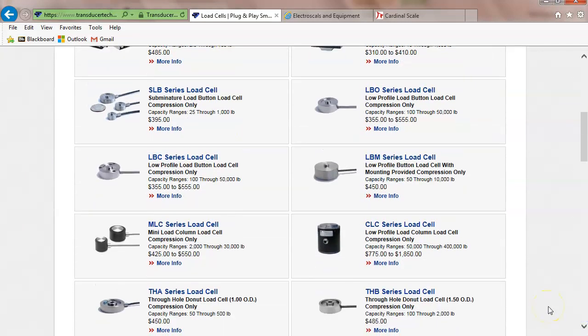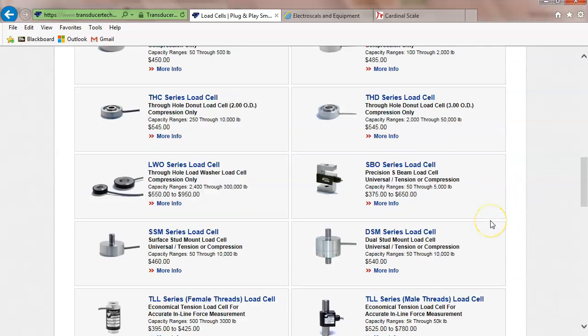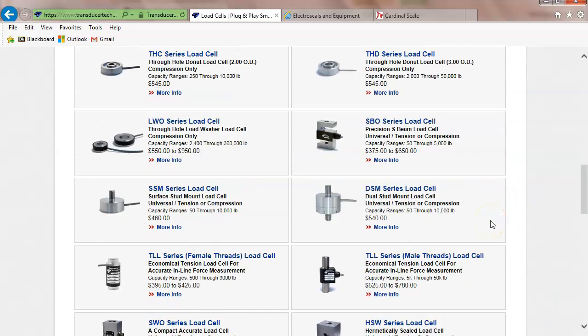So these are the ones that we had on our truck scales. Most of our truck scales, we used the 50,000 pound scale. On our track scales, our railroad scales, we had 6 load cells, and I think they were 100,000 pounds. That might not be right because you can buy these up to 400,000 pounds. But see, they come in all shapes and sizes. All we're trying to do is come up with a chunk of metal that warps with weight, right? You understand that? And then we attach the strain gauges to them.